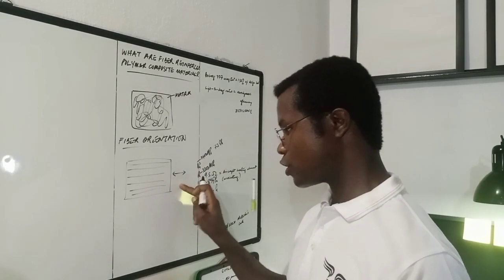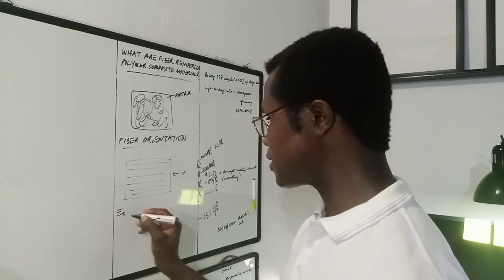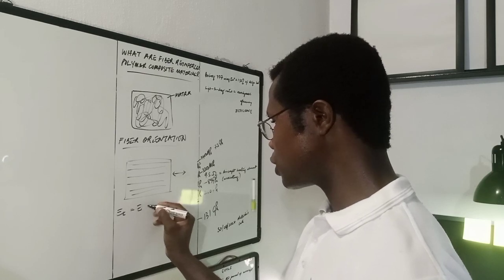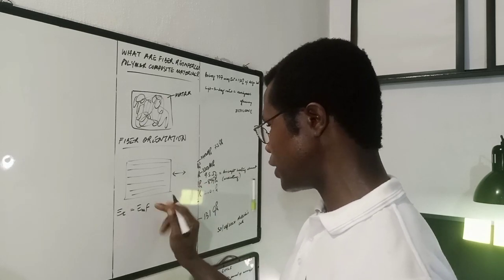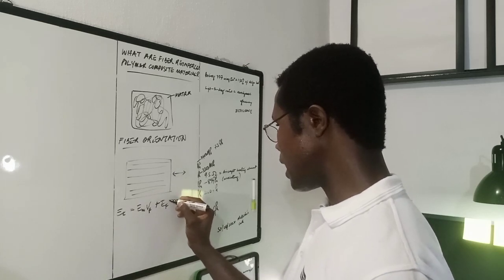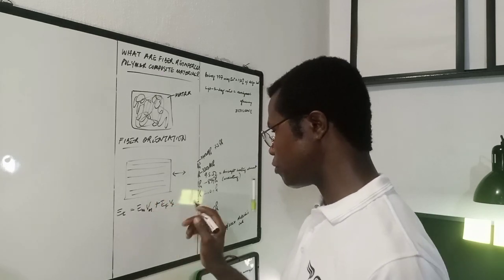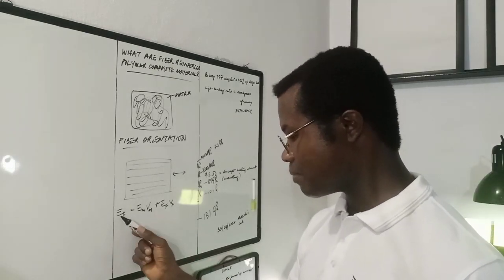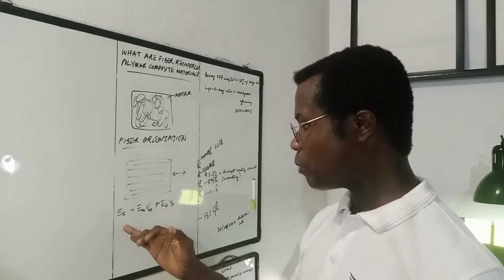The modulus or the strength can be obtained by a simple relationship like this. Modulus of composite is given by modulus of matrix times the volume fraction of matrix, Vm, plus modulus of fiber times the volume fraction of fiber, and I'll talk about what the volume fraction is. So this is the modulus of the composite. If you want to estimate, you can do a back of the envelope calculation, and I often do this to know how much